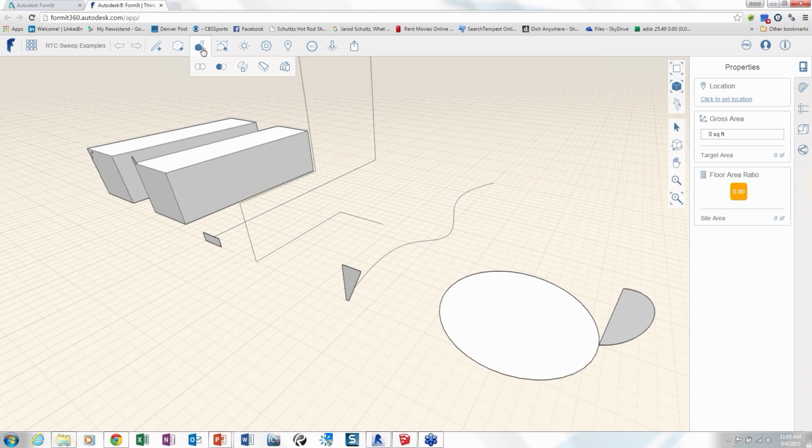A couple things. This has been a big wish list item for a lot of people, and I just want to make sure everybody understands that it's under this little lightning bolt thing here. This is where you have your Boolean operations, where you can add, subtract. But then this is where you'll find your sweep. You have this interesting one, which I haven't seen before in any other modeler, this cover thing. Cover? Yeah, it can be really useful. One thing I use it for a lot is to heal up geometry where I've deleted a face or something like that. I can just choose usually one edge and then use the cover tool and it'll just clean it up for me. But I don't use it as much as I use sweep, that's for sure. And then we'll also talk about Loft.